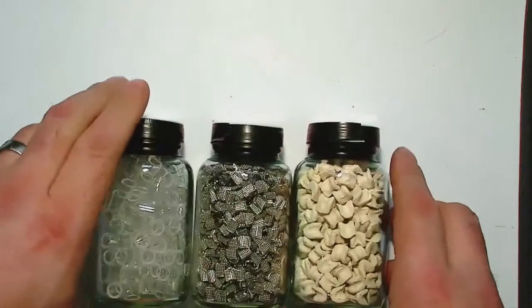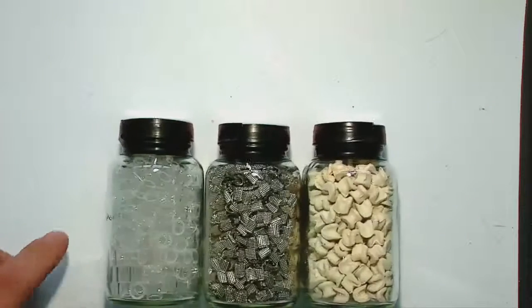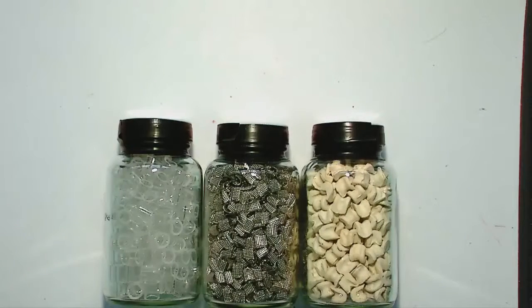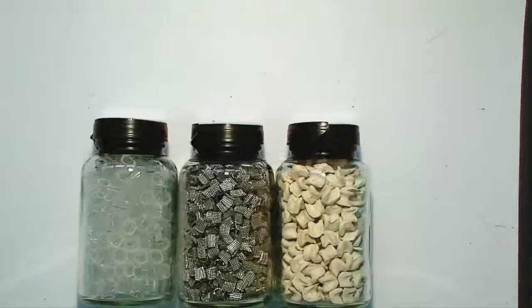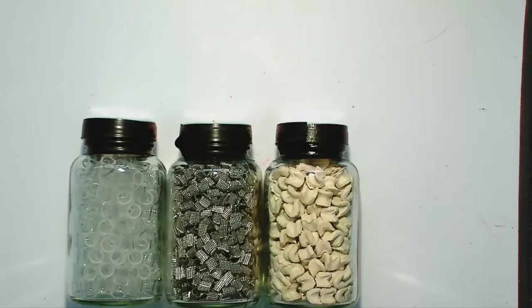And the key things with the packings are essentially, if you remember from distillation, the voidage in your system, and then how much surface area you actually have. So you can see here that there's a whole variety of different materials that your packing can be, okay? And all of these materials can actually be used in a commercial packing, and you need to think about what liquids you have and what packing you need.